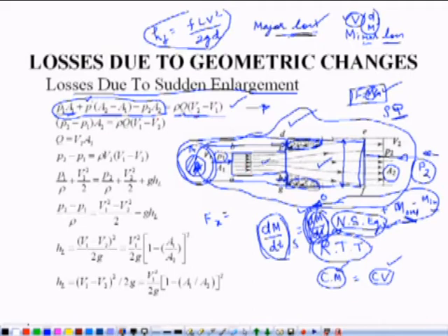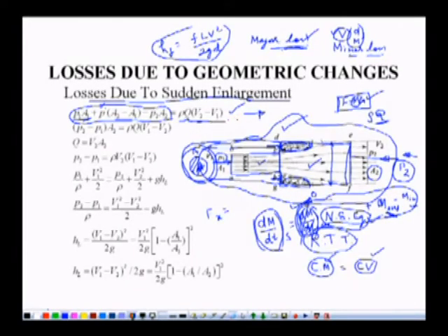On the left hand side we have a force in x direction, and on the right hand side we have momentum going outside the control volume minus momentum going inside the control volume plus rate of change of momentum in the control volume, and rate of change of momentum in the control volume is 0 because flow is a steady flow. So we are only left with these two terms, which is momentum going outside the control volume minus momentum going inside the control volume.